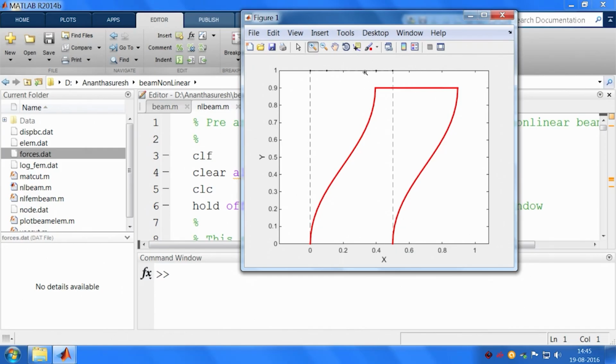Now we have this. So if I have this one as the stage that is supposed to move purely in the x direction, I am not getting it here. When I do nonlinear analysis, which is actually realistic, it is moving down. In order to compensate for that, we add 2 extra beams, which is what we had originally when we opened the file. So let me go back and put those files and then see what happens. Again, instead of having this, I have 2 extra nodes, there is 1, 5 and 6. I am going to have a vertical beam and this.